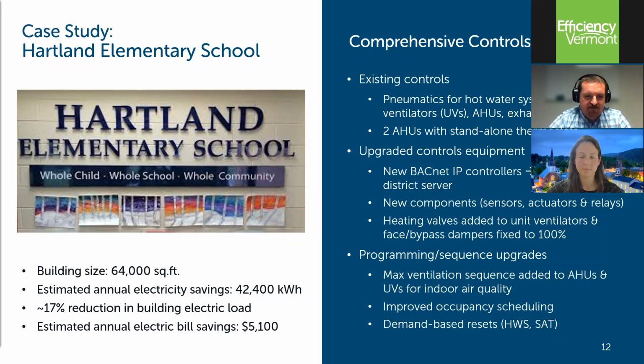The new BAS gave a lot of the modern day functionality that you'll see. So better user interface that they can access from anywhere, alarming, trend data, tighter schedules, more set point control. So it was a huge improvement for the facility staff there, going from the pneumatics to the DDC. We took the opportunity to do some additional program and sequence upgrades.